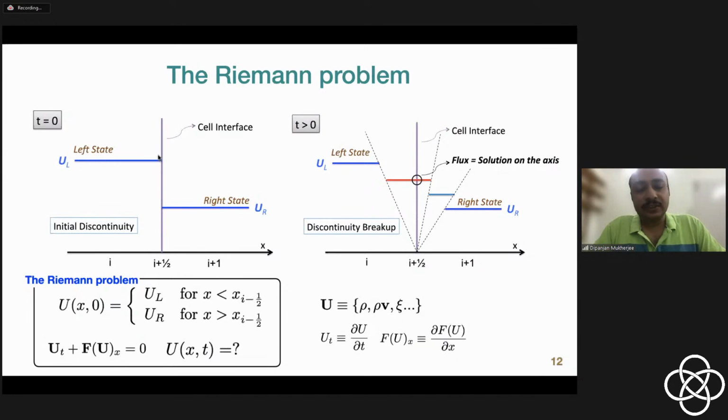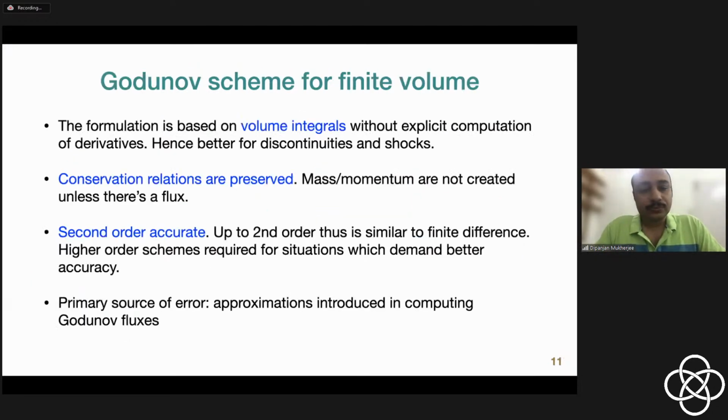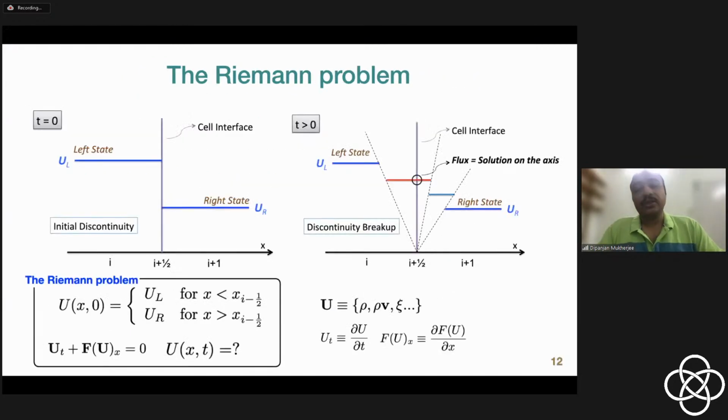So this is the interface between these two cells, and if you have differences between these quantities, you can solve this Riemann problem. And there are well-defined schemes to find out the evolution of this quantity described by this problem. Essentially the main problem of fluid simulations boils down to solving the Riemann problem at the interfaces of different fluid cells.